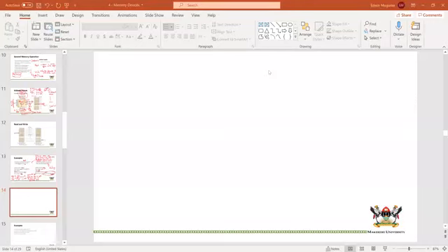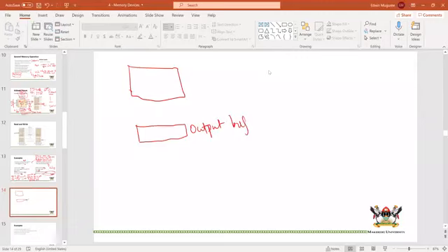High Z, and so you have, this is your memory, for instance. And then you usually have what we call output buffers. By the way, these output buffers also sometimes have a chip select. Let's say they are 4 bits. So this is your memory. Even if this memory appears at the inputs of the buffer, this is called an output buffer. And these are your outputs.